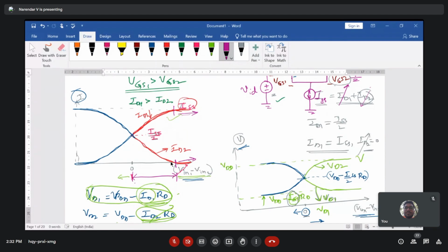It means when your differential input is within this limit, your differential amplifier will respond to the input, and after that there is no change in the current in your differential amplifier, and no variation in your output signal. It means it can accept the input, but it cannot respond at the output because the outputs become saturated.